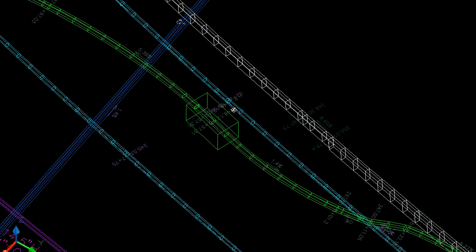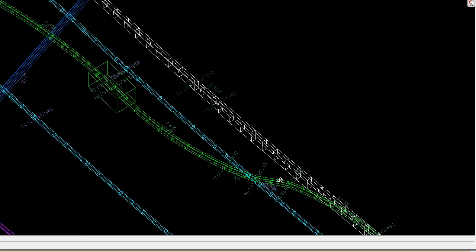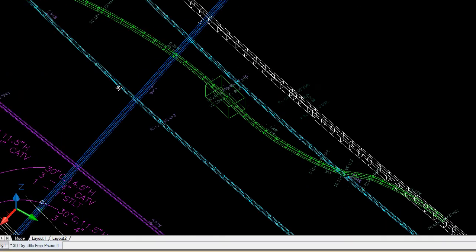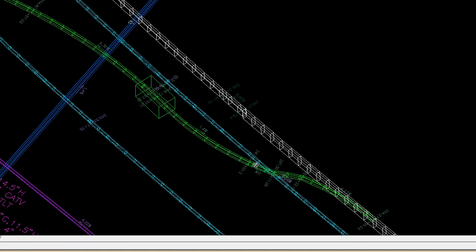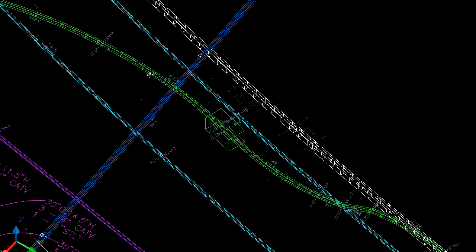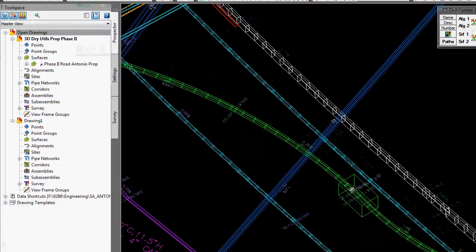You don't want your design changing because some surface changes in the future. That messes everything up because I've got all kinds of custom tweaks done here. If I want to modify this again, it's real easy to just say, hey, delete out the PVIs from here to here, recut the surface from here to here, and I can bring that back in. I've got a lot of options like that, but I don't want the thing doing it on its own. I need control of it, and any other way than that, things kind of get missed is the real problem.